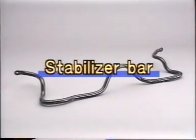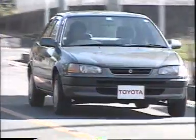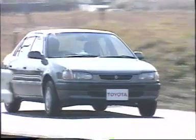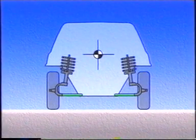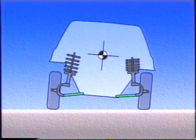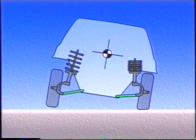Next, let's take a look at stabilizers, which reduce the rolling of the body during cornering. When the vehicle takes a curve, the body leans toward the outside of the curve because of the centrifugal force. If the body leans too much, riding comfort will be reduced and the wheels will lose contact with the road surface, making the vehicle unstable. Independent suspension is particularly prone to such problems.